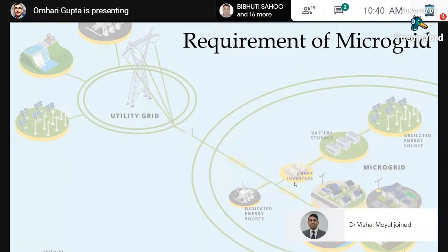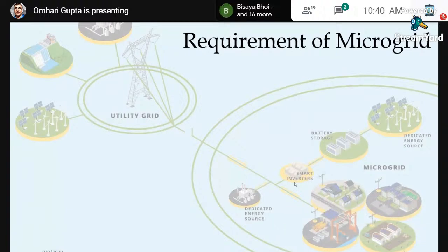Okay. Second, if you do not have sufficient power generated at the local end with the help of distributed generation, then you can disconnect your distributed generation, or we can say DG. Okay, if you do not have sufficient power, you just disconnect the DG so that the sensitive loads may not get damaged, because there are requirements that the voltage and frequency should lie within these limits. Those limits we'll be discussing later on. So that is a brief about the concept of a microgrid.